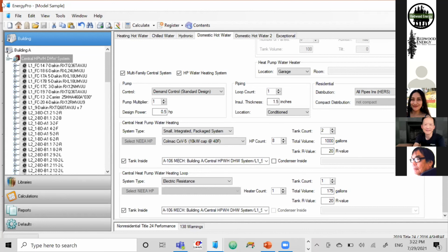So you can get a building permit even though the system has unmet load hours. Yes. That's what I was saying, but it still means you need to go back and fix it. Or, you know, sometimes engineers deliberately undercool areas. I just heard an engineer speaking on that a couple of days ago, where they decided to take in night cooling, which might not be modelable, or do their off-sheet calculations outside of the software and feel like they can defend their analysis. And so they got a stamp, and the software perhaps allows that to happen.